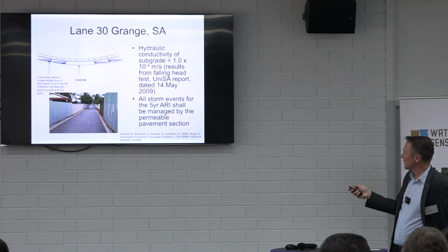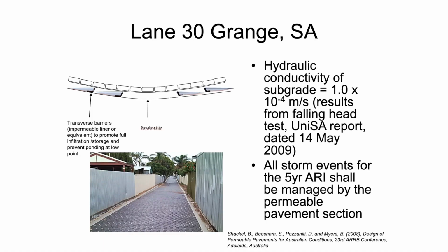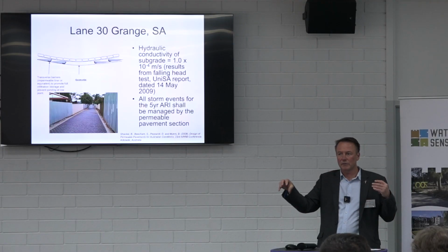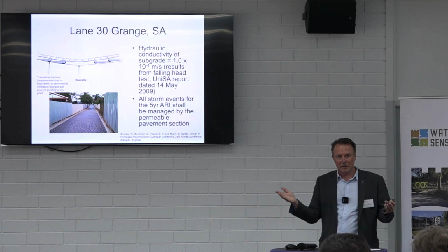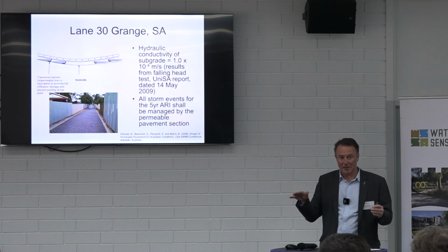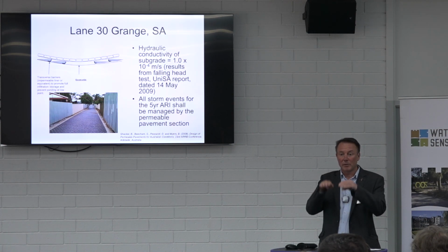Very innovative design, this one. You can't really see it in that photograph, but it's actually dish-shaped. In a permeable paving system, from the way hydraulics works, you'd actually get ponding in the middle during storm events if you're not careful. It will quickly dissipate, but that would be the area that will clog first, that middle bit. You don't want that to be the first place to clog, you want it to be the last place, because if that clogs, you'll get permanent ponding there.